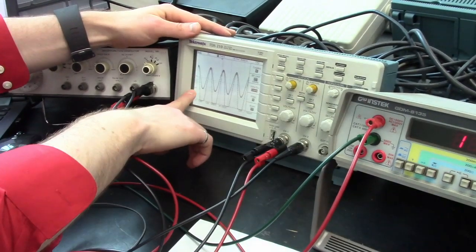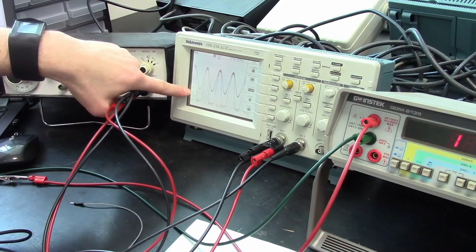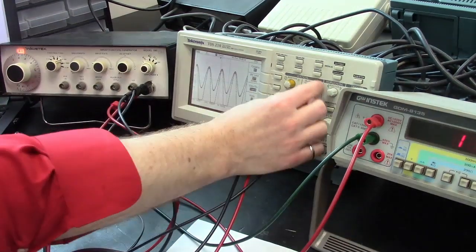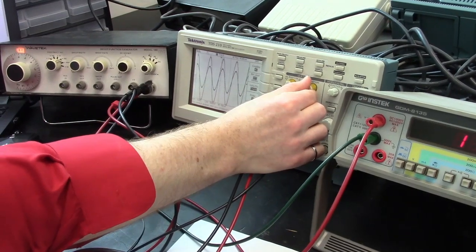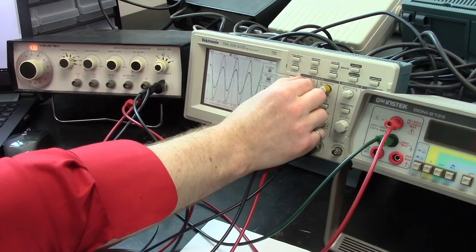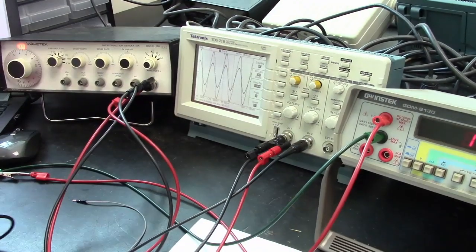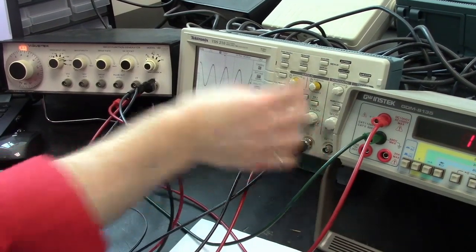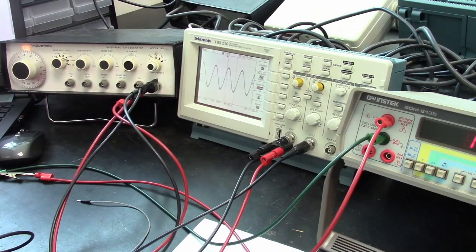And we have a DC offset. You see the center point of channel 2 is lowered down. You can move that with this vertical position adjustment, moving that back to align with channel 1 there, to be both centered around 0, and then reducing the amplitude, and they should overlap, and they do.